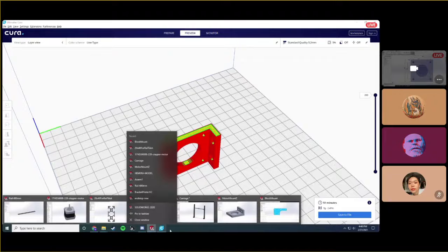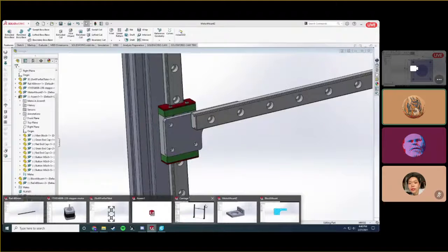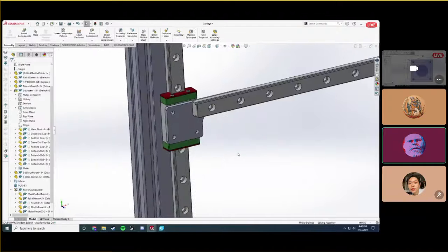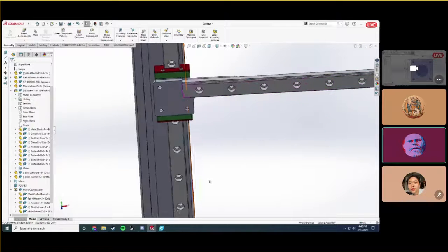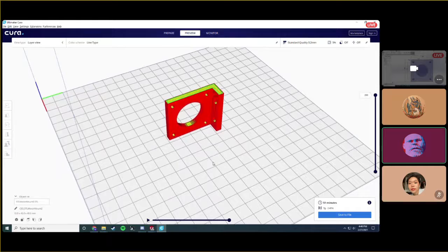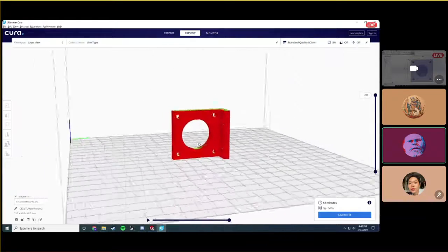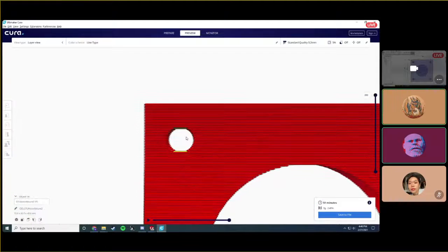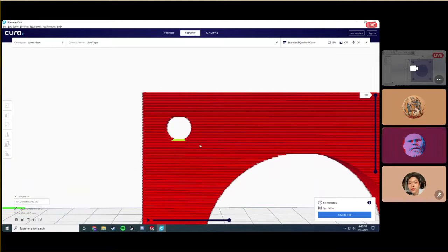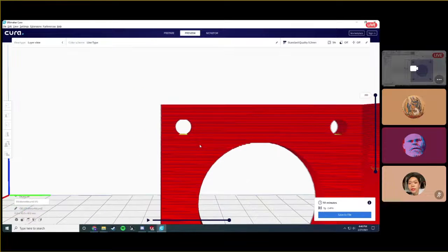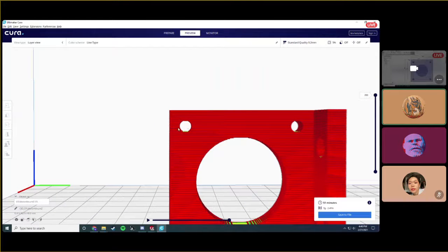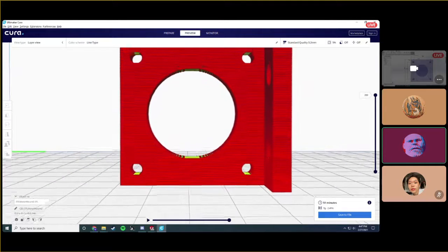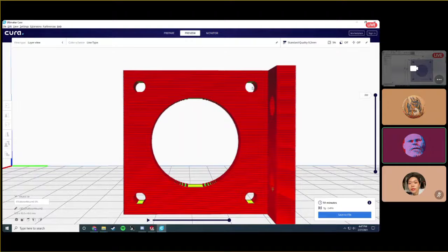So yeah. Is there anything else you think I should go over, Jason? Yeah, go back to the 3D print real quick. I just want to cover one thing. If you were to look at that circle, those aren't going to be real circles. They're not going to be perfect circles, at least. You can see it very clearly there. They're going to be slightly ovals. And that's why it's nice to make them a little bigger than they need to be, just slightly bigger. Just because of the accuracy of how the 3D printer moves.